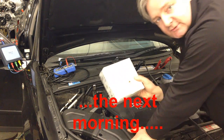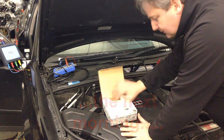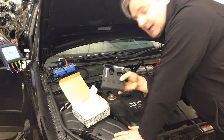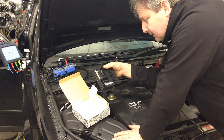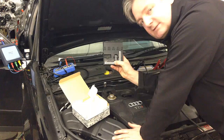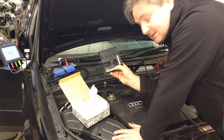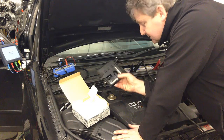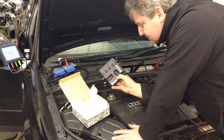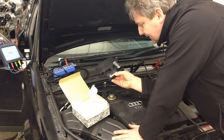So, parts just arrived from the Volkswagen Audi parts supplier, so we've got a new onboard power supply control unit that's arrived today. What we're going to do now is fit this unit on. Looking at the unit itself, from the part number that we got yesterday, there is a supersession, so the suffix, the final part, the letter at the end of the part number, is different. Obviously it's had some sort of revision. We've got a production date of 21st of 5th, 2014. It's made in Romania with the genuine Volkswagen Audi logo on it.